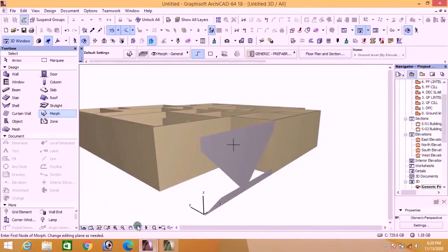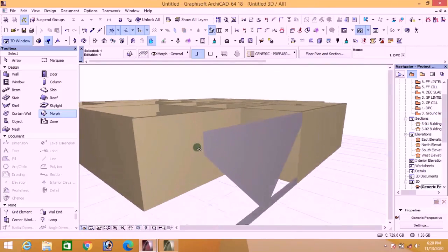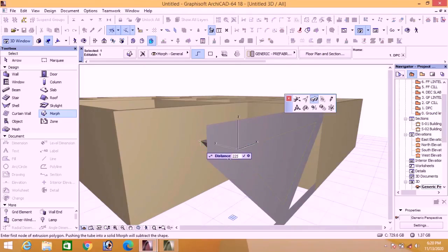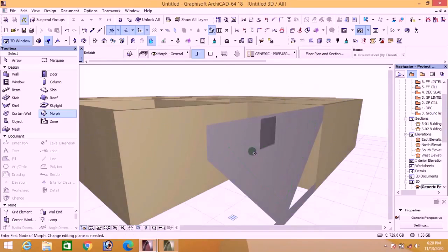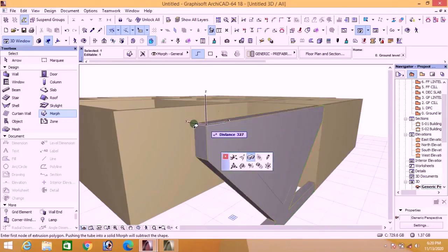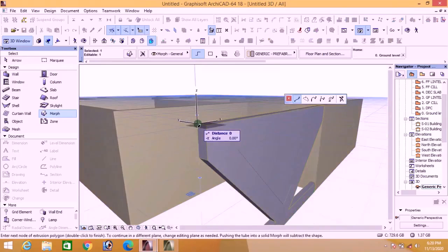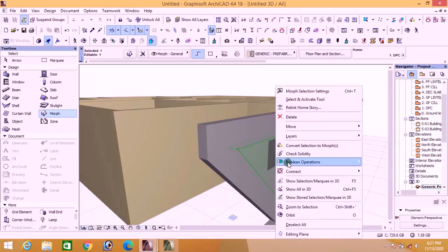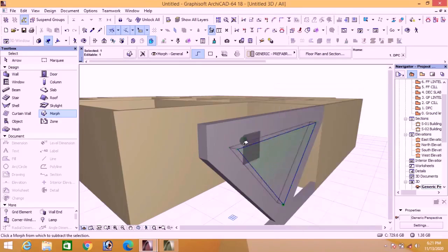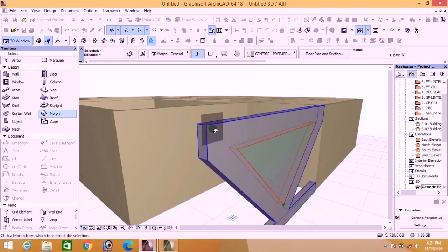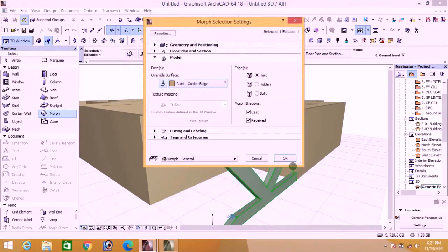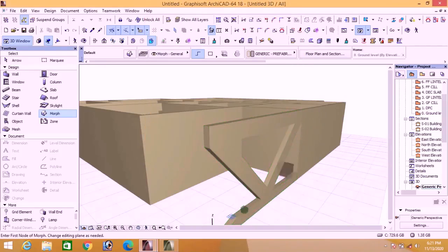Let's extrude it into a solid. First of all, extrude this to 225. Also extrude this to 225. Having done that, to open this place, click on this second morph that is inside here. Right click on it and go to Boolean operation, move down to subtract. Click on subtract, then bring the cursor on this bigger morph here and click on it. That place will be open. Then change the material to your building material. That's done.